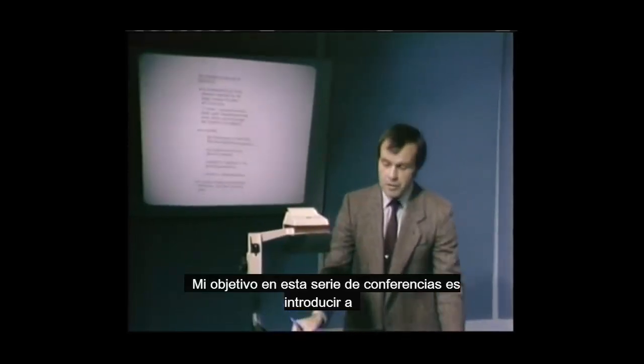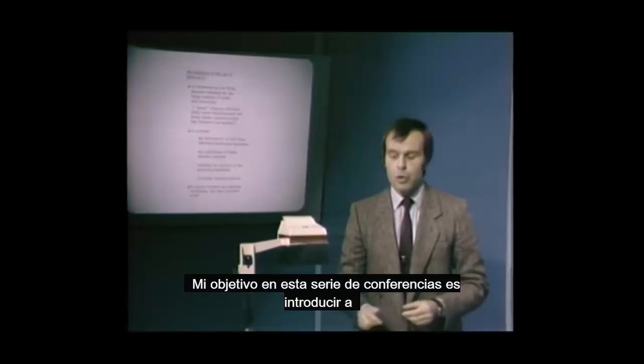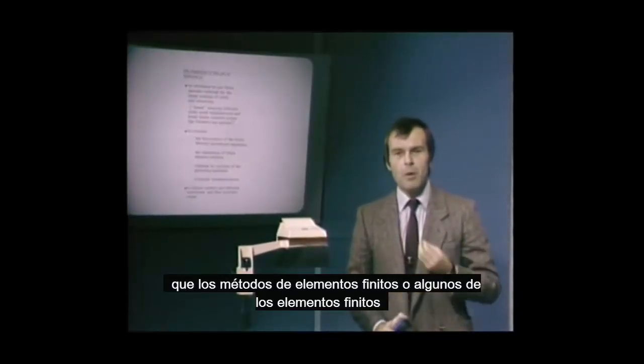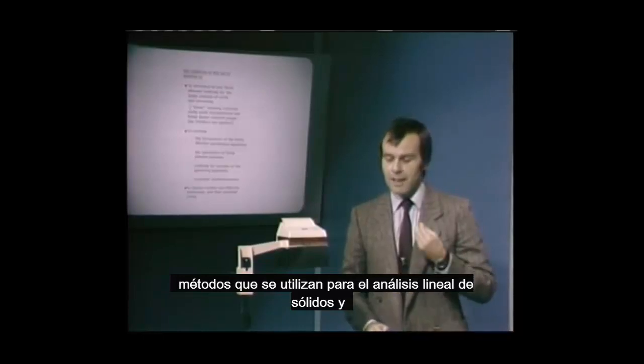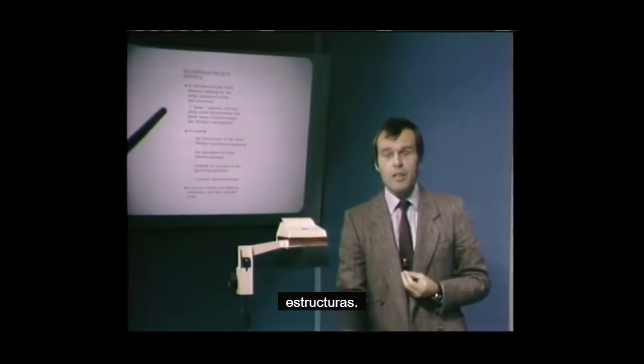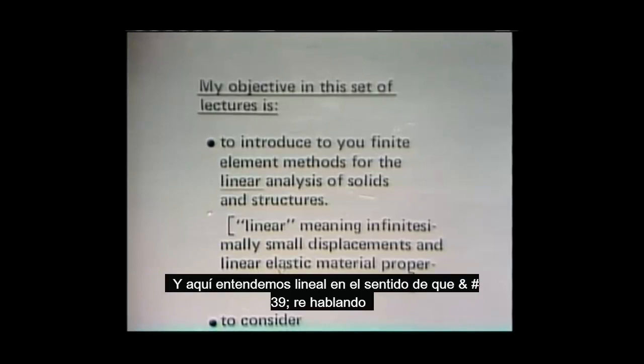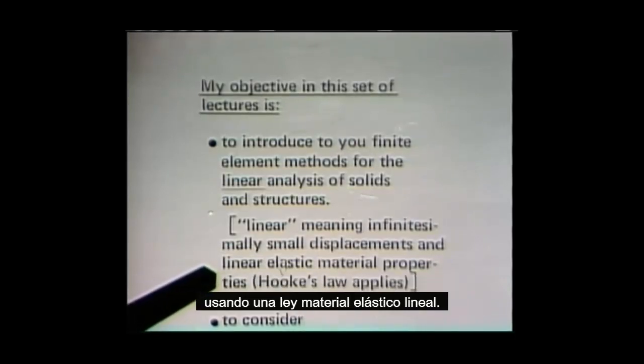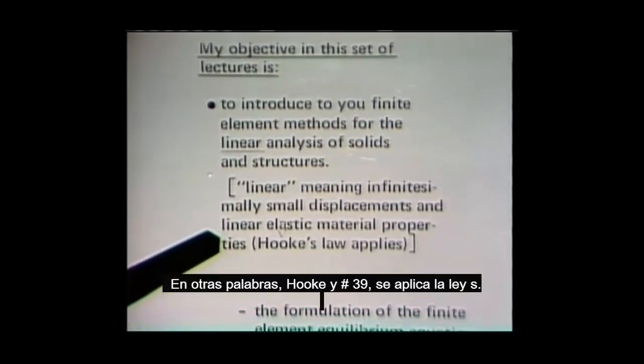My objective in this set of lectures is to introduce to you the finite element methods, or some of the finite element methods that are used for linear analysis of solids and structures. And here we understand linear to mean that we're talking about infinitesimally small displacements, and that we're using a linear elastic material law. In other words, Hooke's law applies.